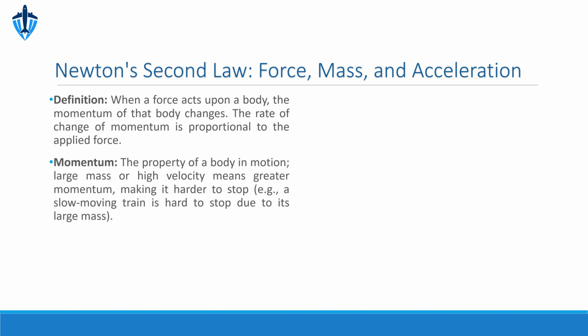Let's consider an example. If we need to lift a 500-pound weight with a lever where the resistance arm is 12 inches and the effort arm is 60 inches, we can calculate that only 100 pounds of effort is needed. This results in a mechanical advantage of 5, meaning you get 5 times the output force compared to your input.